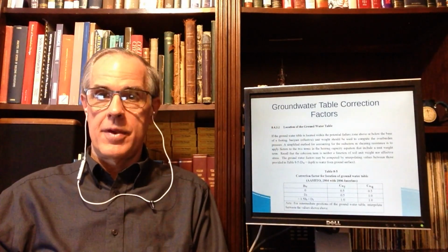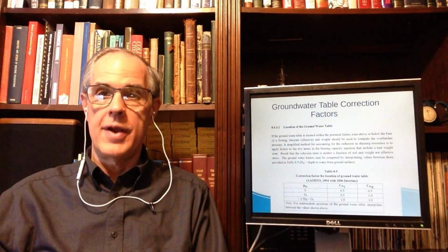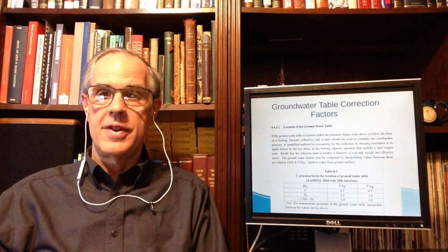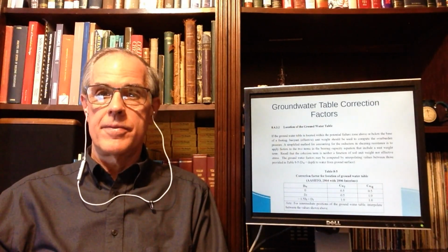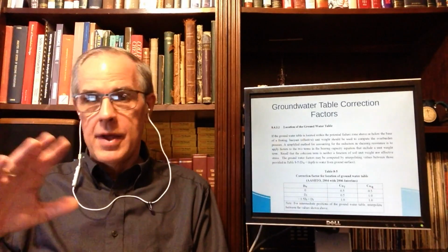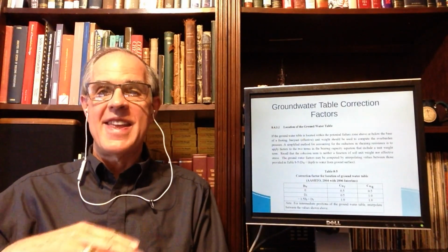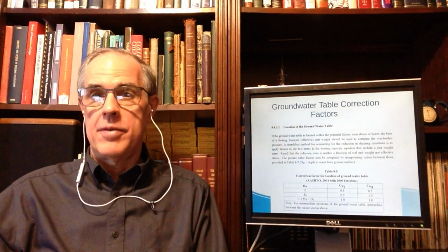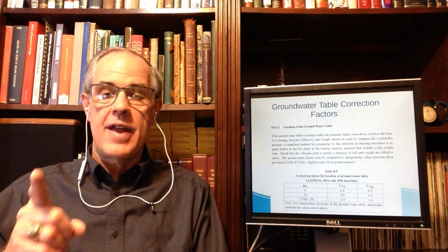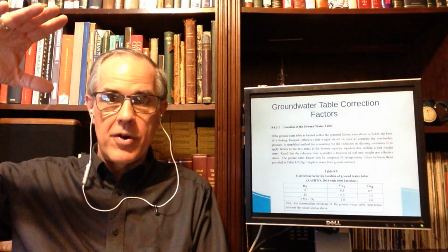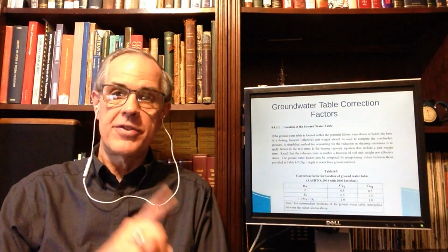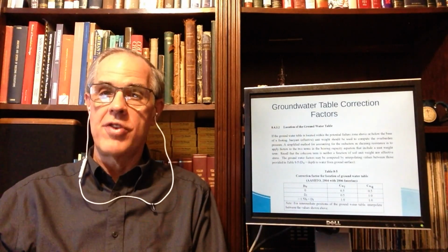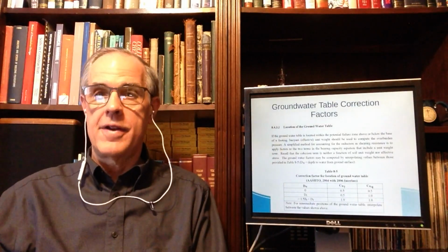You will recall back in soil mechanics we talked about submerged unit weight. And you will recall that I said that many times the back of the envelope assumption is that the submerged unit weight can be guesstimated to be, in many cases, half of the saturated unit weight. And as a result, if you've got a completely saturated, submerged system, then the effective stresses are cut in half. That's the governing assumption behind this. It does not affect the cohesion because in Mohr-Coulomb theory, cohesion is unaffected by effective stress and unaffected by changes in the groundwater.